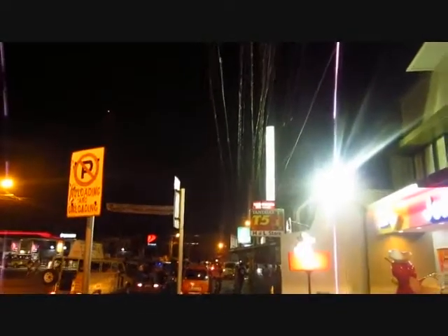Loads. Loads of power systems are divided into industrial, commercial, and residential. Very large industrial loads may be served from the transmission system. Large industrial loads are served directly from the subtransmission network, and small industrial loads are served from the primary distribution network.